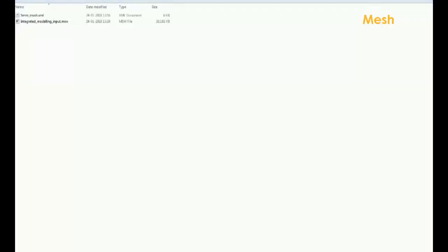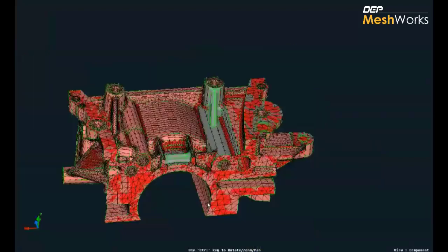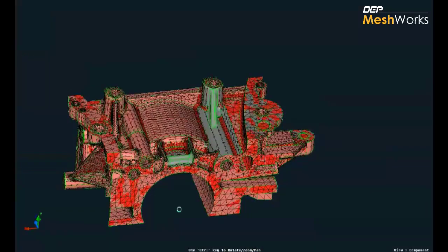Let me give a mesh template. And then say update FE model with changes. So this is a stage where it locally identifies, meshes the identified surfaces, and then stitches and updates the dependencies. So in a moment, we will see that also. So this is going to be a very useful tool, since the associative modeler is a scenario which is being used very frequently by almost all OEMs and customers.